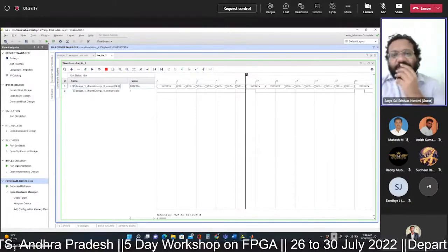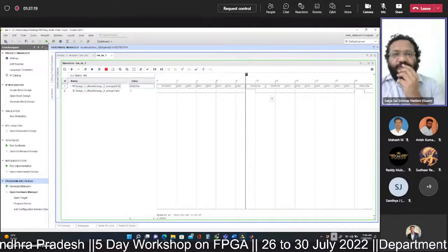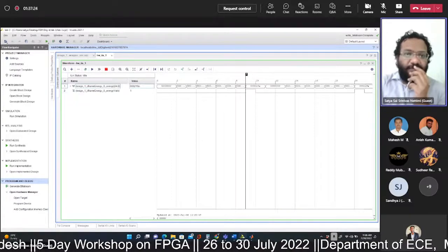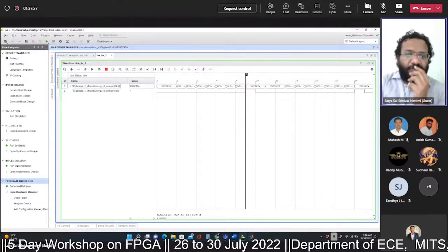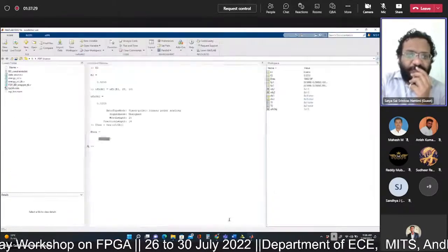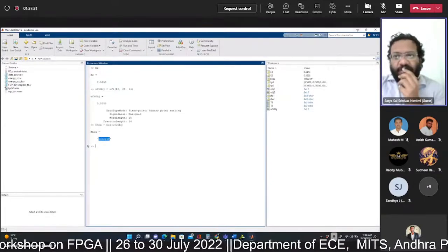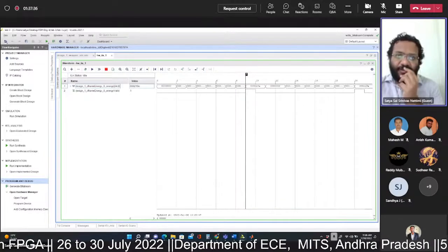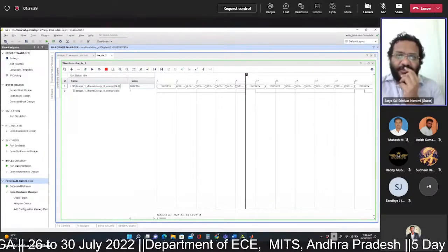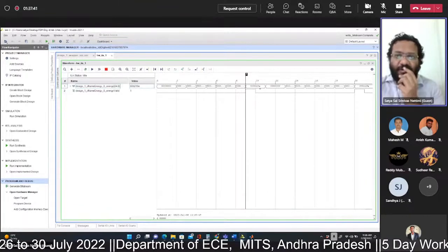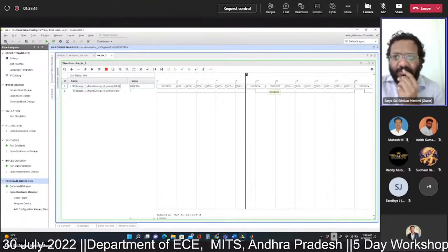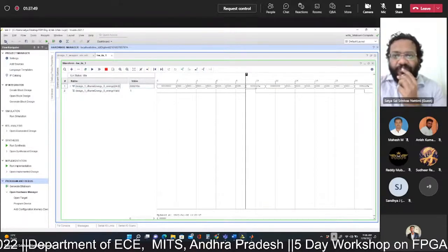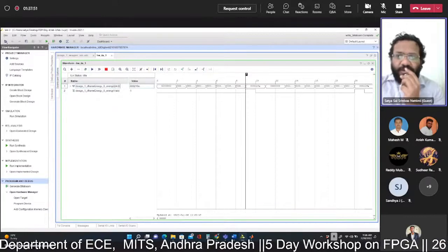The same thing when computed in hardware is 000219E. Instead of F, we got E. Why? Because of truncation error. MATLAB has calculated the value in floating point, and that floating point is converted into fixed point. But in our hardware, even the signal sample values are in fixed point, and we used those fixed point values to compute the energy. So we got nearly equal values. The error is very small, so we are able to calculate the energy value accurately.